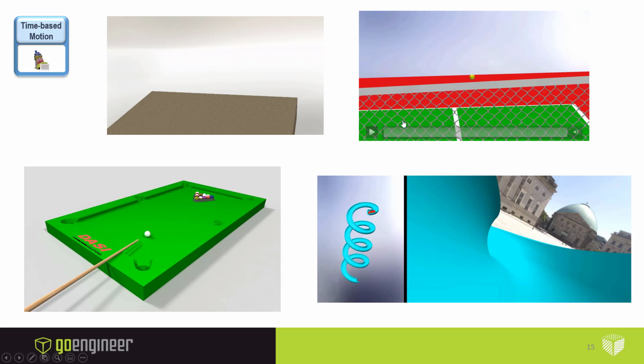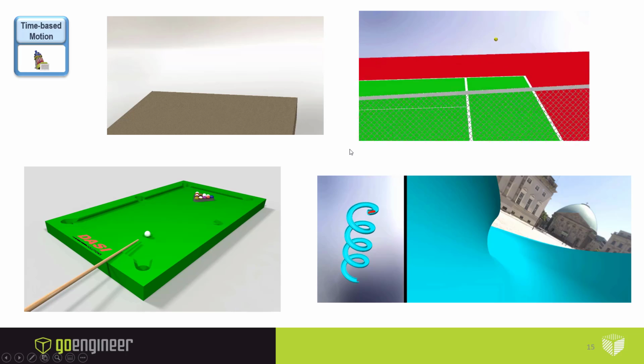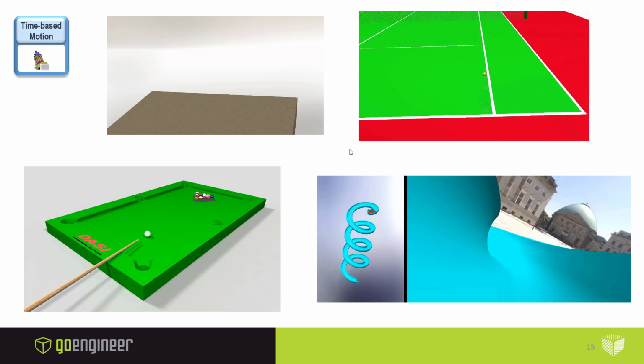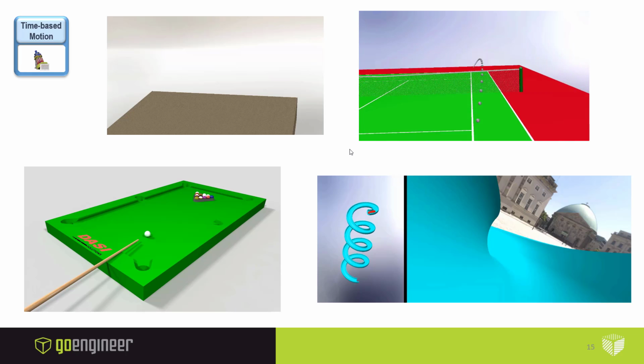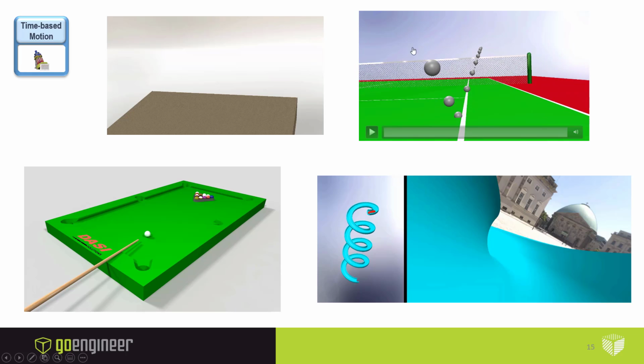Here's an example with a tennis ball that's going to curve. You're going to see this tennis ball curve in midair, and the curve is going to be based on its rotation. Depending on how it rotates, it'll curve. That's because I put a force on this tennis ball, a force that depends upon the direction of rotation and the rate of rotation. So I included drag and lift forces. You'll see this ball's hit, it's got some spin on it, it curves around and lands in the singles court. You can kind of tell that curve there. And this was using a trace path inside of SOLIDWORKS Motion. You can look up trace paths if you want to show that kind of stuff. You can show projectile motion using SOLIDWORKS Motion if you want.